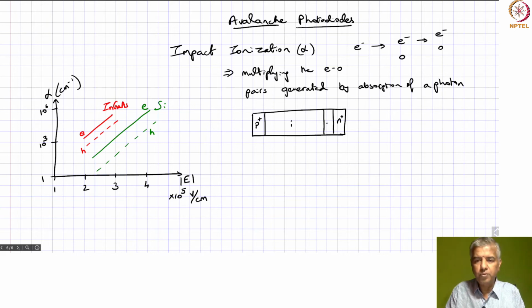Now what if we can add one more layer over here, a p-type layer? What happens in this sort of case? Well, of course we know that because of the charge transfer that happens at these interfaces, from the p-type I'm going to leave behind some negative charges over here.